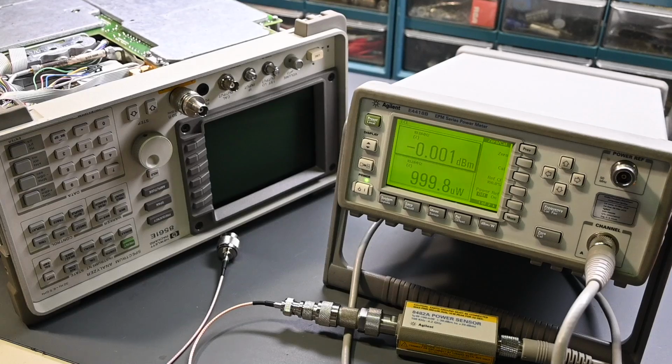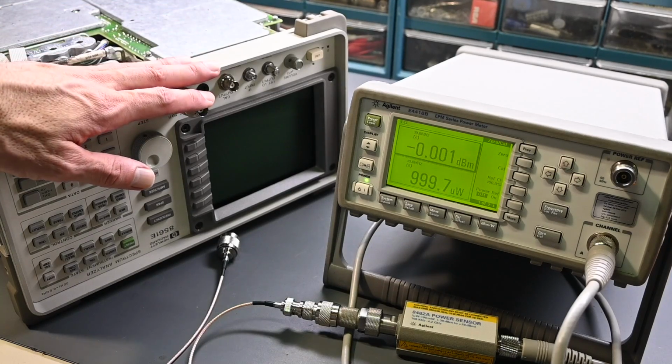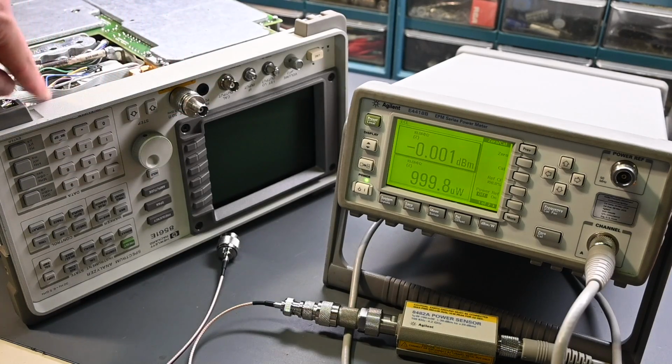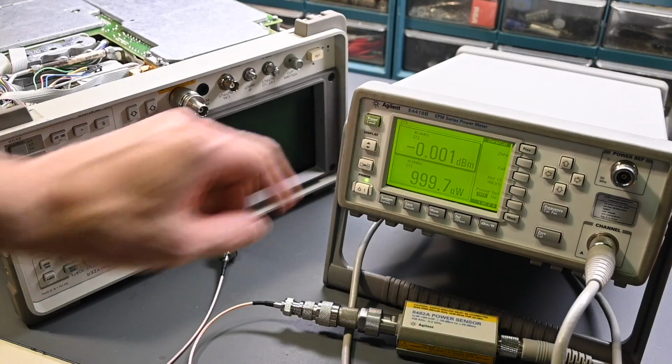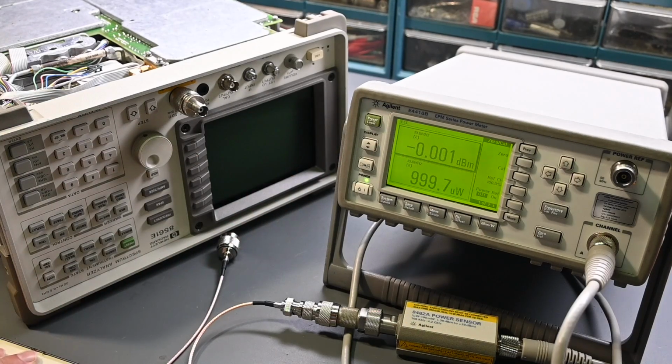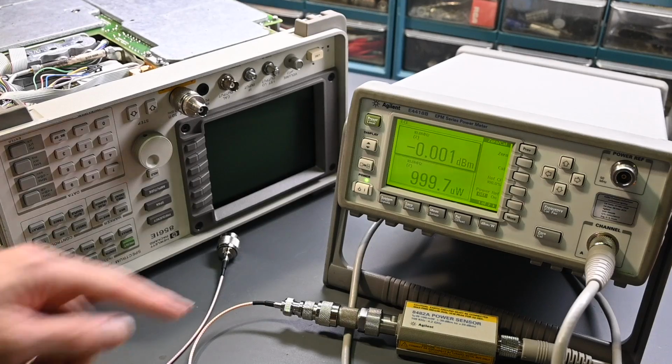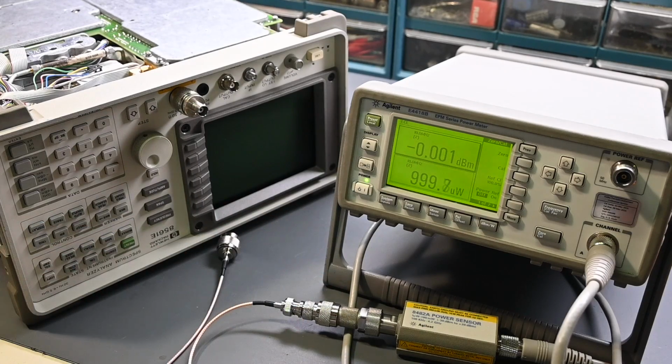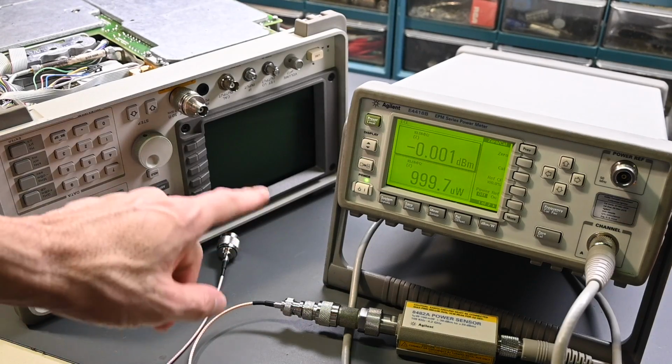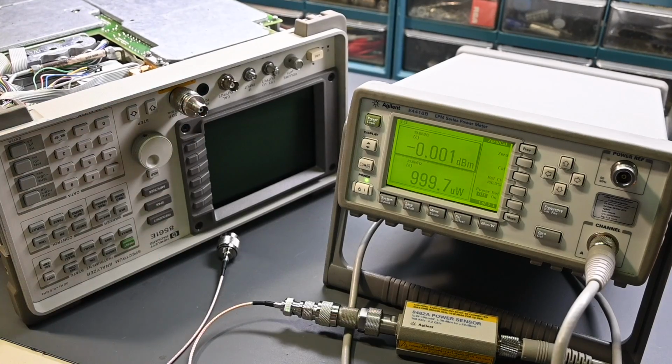Okay, I want to apply a 0 dBm signal into the spectrum analyzer, which will just be going through the RF attenuator, and then we'll measure the output of the attenuator on the power meter. So I have the output from the Rohde & Schwarz SME06 going into the power meter right now, and you can see it's set to 0 dBm. Now, the actual output from the signal generator is just a little bit higher, by a very small amount, and it's compensating for the loss in the coax cable between this point and the output from the signal generator. So that assures that we're getting exactly a 0 dBm input here.